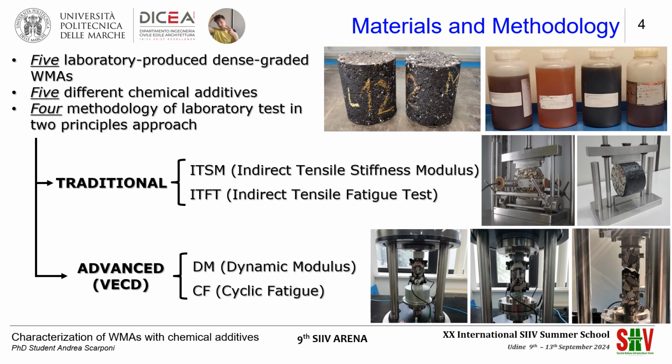The first one is the traditional, which is composed of the indirect tensile stiffness modulus and the indirect tensile fatigue test. Then, to evaluate the viscoelastic continuum damage, I use the advanced approach called VECD, which is composed of dynamic modulus and cyclic fatigue.